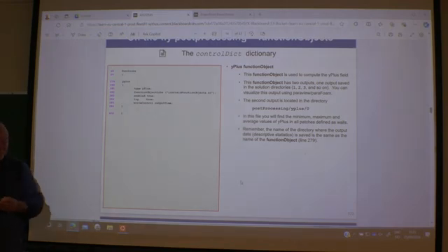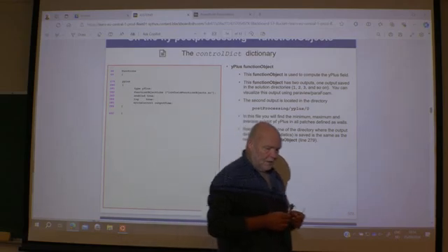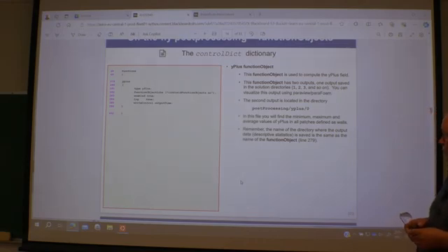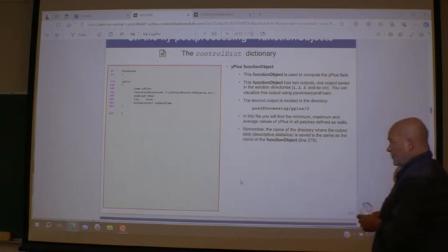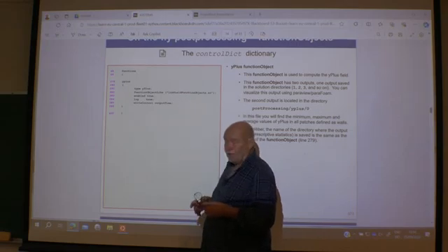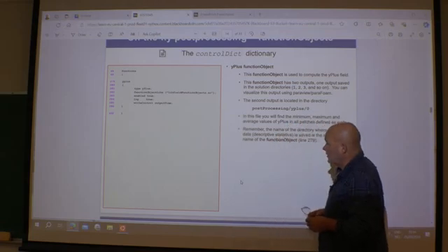And here then, maybe very interesting, how to write out the y plus. Of course, instead of using these functions, you can do it afterwards. When the simulation is done, then you can also calculate the y plus and also get, well, any of these other functions as well, actually. But it could be nice just to include it directly so you have them all the time. It could be a good idea.